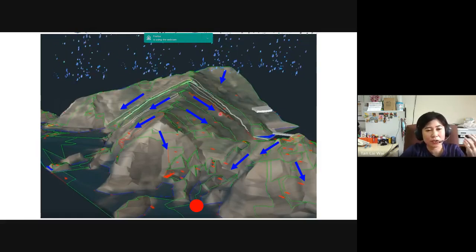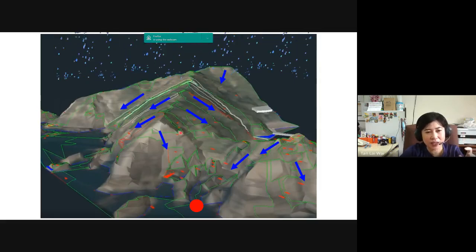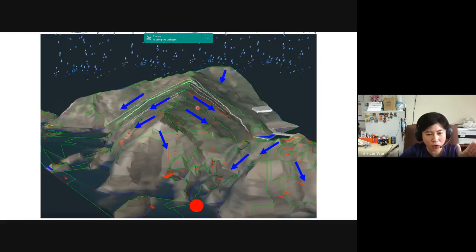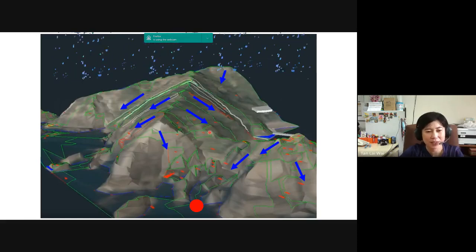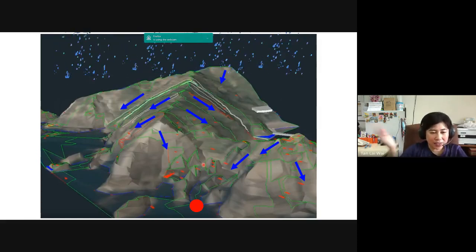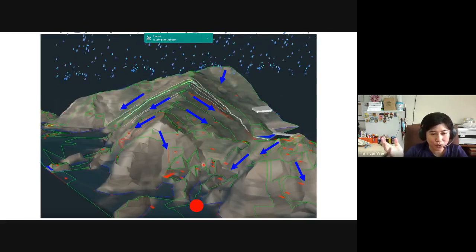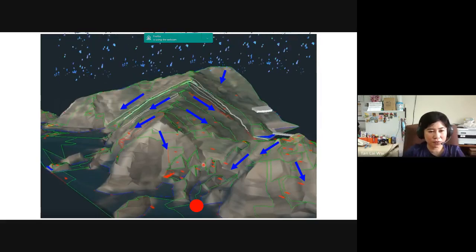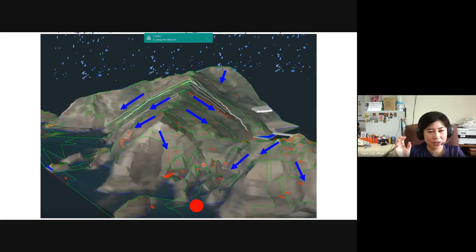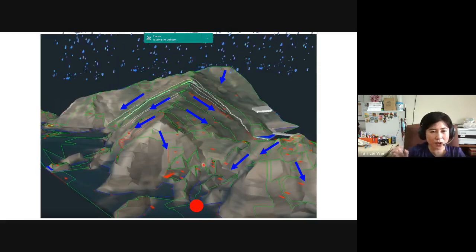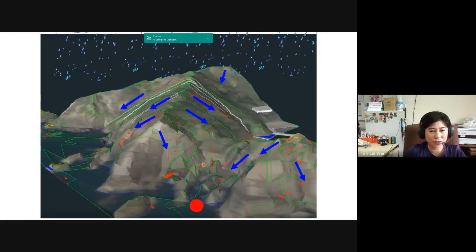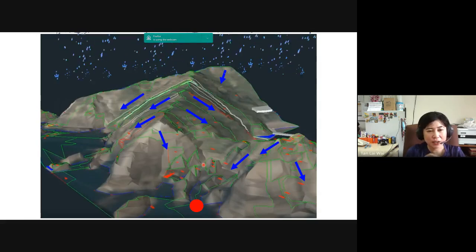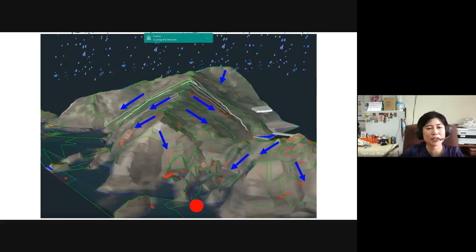If you have pavement, your C value is higher. If you have forest land cover, your C will be smaller. That means more rainfall runoff will be intercepted. Now, divided, I hope by now you should know why your rational formula is divided by 360. You convert your A, the area, from hectare, and your I from millimeter per hour. You convert it and divide, that means you are converting it into cubic meter per second. So therefore you divide it by 360, you'll get meter cube over second.